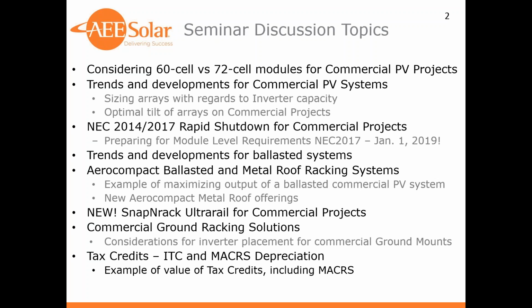A big concern rolling into the second half of the year, and especially for January 1st, 2019, as we end this year going into the next one, we'll be preparing for module level rapid shutdown requirements as required by NEC 2017 on states that are adopting or are on that code cycle. We're also going to be looking at ballasted systems and any trends that we notice there to ease and speed your installations and lower your installed costs for you and your customers.